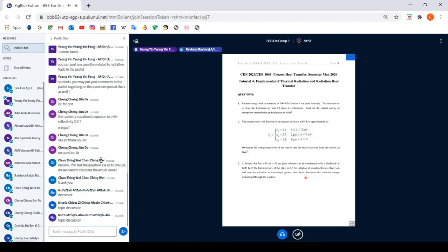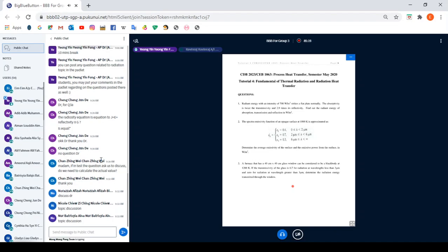Then maybe we have to use both concepts, right? Yes, both concepts. But in the upcoming heat exchanger topics, you will usually focus on the overall heat transfer coefficient, the U value, that I will explain to you. I think next week we will start the heat exchanger topic. In fact, the U value is a combination of the internal heat transfer coefficient, the h value, and the external heat transfer coefficient, the h external. Okay, sorry madam. Thank you, madam.